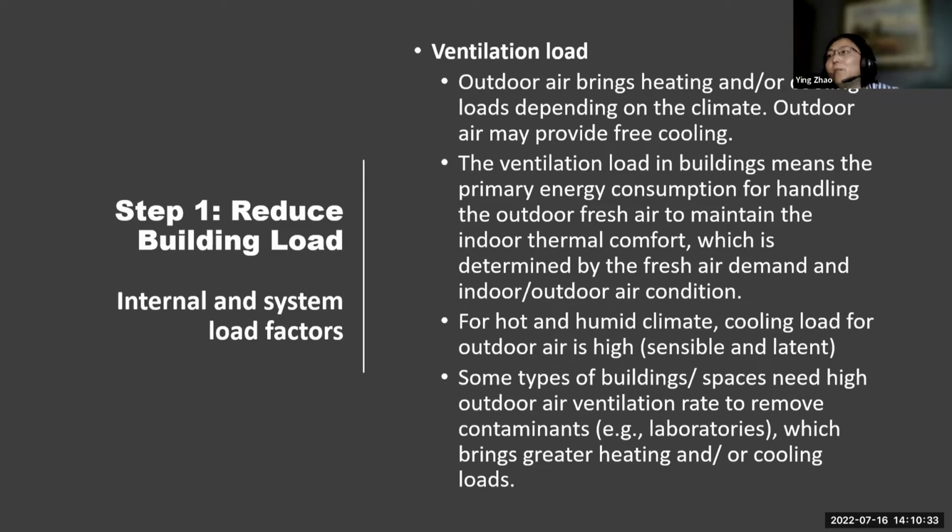For hot and humid climate, the cooling load for outdoor air is high, because it includes both sensible and latent heat gain. So for a hot and humid climate, the ventilation load will be an important part.